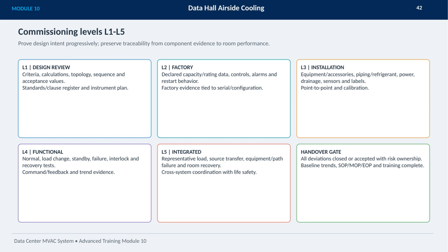Moving to L2, factory testing ensures declared capacities, control logic, alarms, and restart behaviors are documented and tied back to specific serial numbers and configurations. When we reach L3, installation checks cover equipment, piping, power, sensors, and labeling with thorough point-to-point verification and calibration.